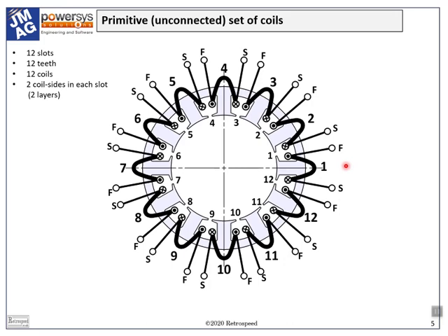But this would be too powerful a tool to use here, and even if the winding layout were produced by a mathematical algorithm, we would still have to make many practical decisions. Curiously enough, many of those decisions would concern the interconnectors or jumpers, and they are factory decisions that would hardly benefit from a mathematical approach. If you ever have the chance to visit a winding shop, or especially a rewinding shop, I'm sure you'll see what I mean.